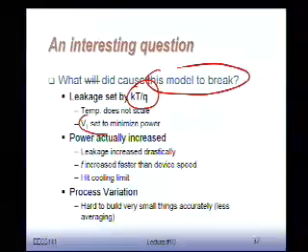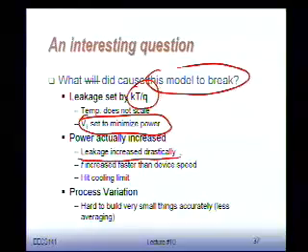So we have to set a certain VT. VT is a function of your kT over q factor. There's only so much you can do. And we cannot scale VTs that much anymore as a result of this. So this has been a problem. We have scaled thresholds, but as a result of that, leakage has increased radically. And we have hit some cooling limits as a result of that.